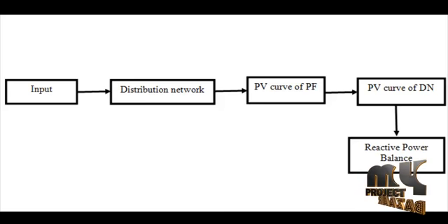The minimum voltage is noted as the critical voltage. Taking the critical voltage point as a reference point, the load reactive power voltage curve is divided into two sections. The absolute value of dQ by dV in the left section is greater than that in its right section. In the steady state, the input power and the load power at the bus 3 are kept in balance. So the operating voltage of the bus 3 is determined by the cross point of the power grid transmission characteristics and load reactive power voltage characteristics.